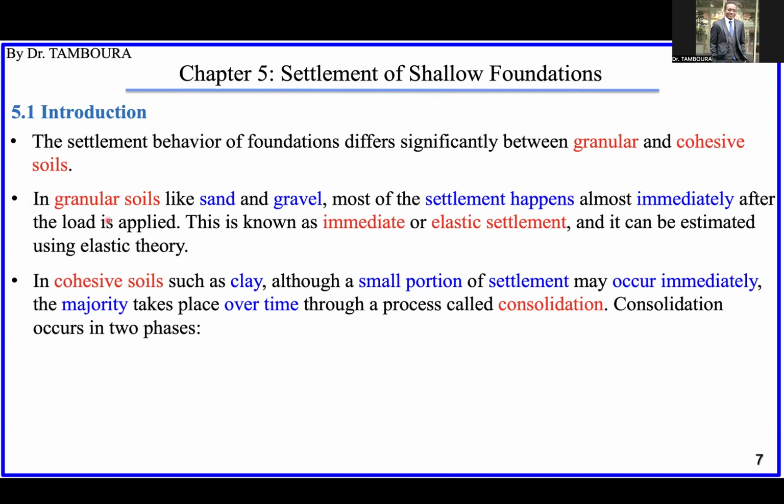That was granular soil. In contrast, in cohesive soil like clay, the settlement that will happen immediately after loading is very small. The majority of the settlement will happen over time.